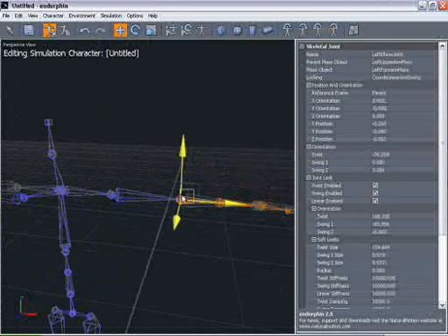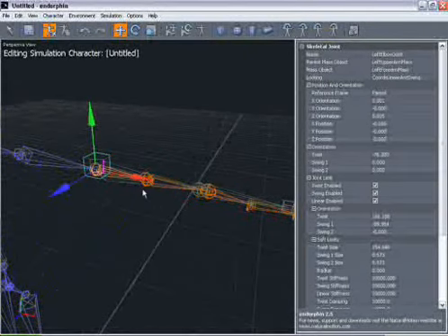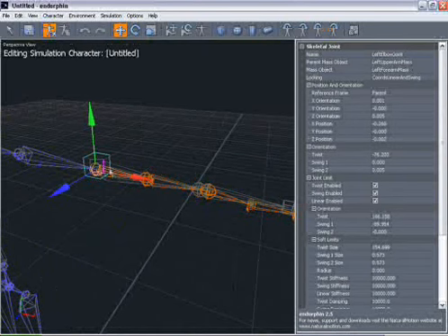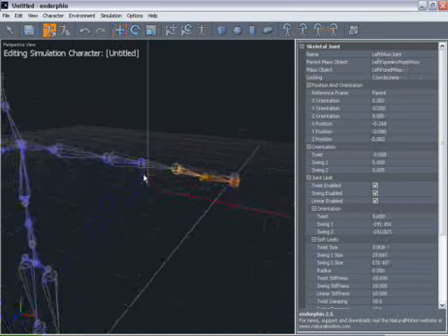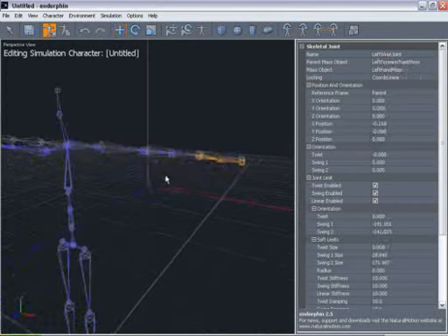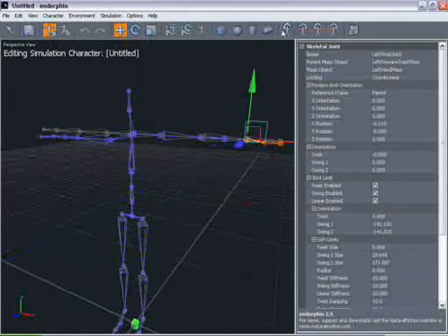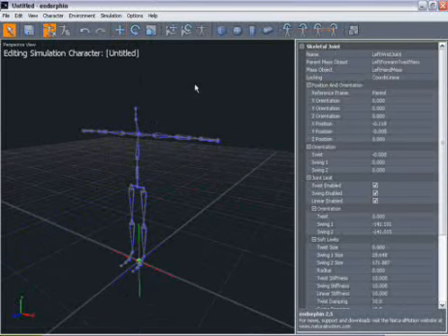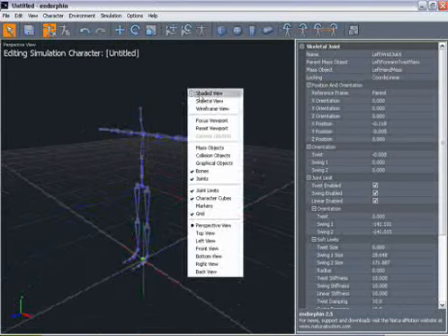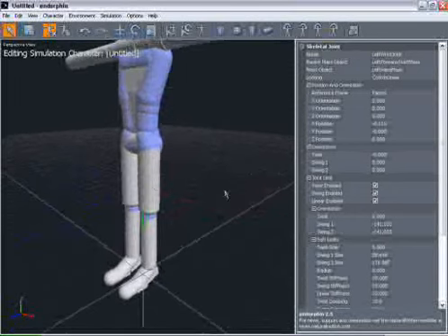Elbow, and again you can see we've got an extra joint here for the forearm roll, so we again just leave that halfway in between and then snap the wrist, leaving the hand as it is because the reference character doesn't have any fingers. So mirror left to right, and there we go, we have the two skeletons matching up. So we go into shaded mode, so that we can see that we've got two characters matching.